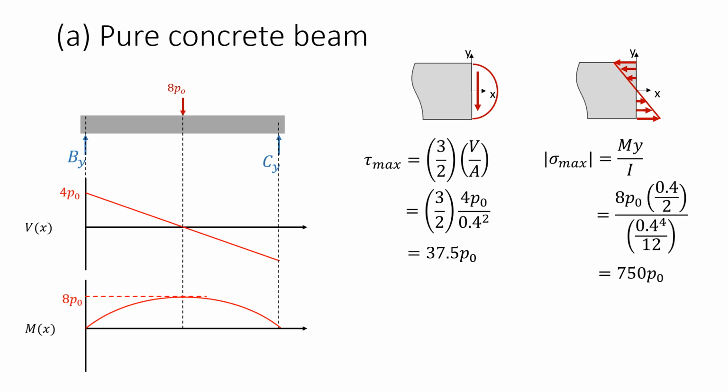Our shear stress is largest at the ends of the beams near the neutral plane. In the middle of the beam, the flexural stresses are dominant, and the shear stresses are negligible. So we can conclude that the failure will occur in the middle of the beam, and the shear stresses can be neglected, which is exactly why I chose this particular loading condition.